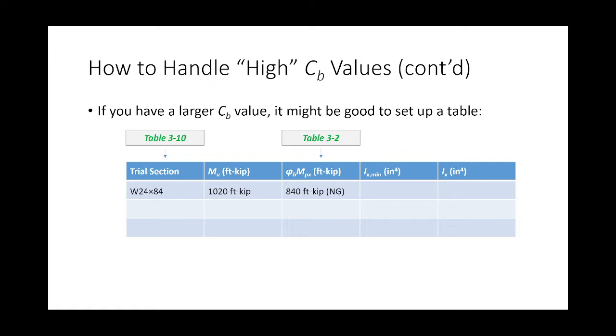And we got that from table 3.2, right? Now, keep in mind, we do have a moment of inertia requirement of 2,800 inches to the fourth, and so you might ask, well, what's the moment of inertia of this shape? Who cares what the moment of inertia of that shape is, because it doesn't work, right? But I just want you to keep in mind that this is something that we have to look at as well. So we go to the next section.